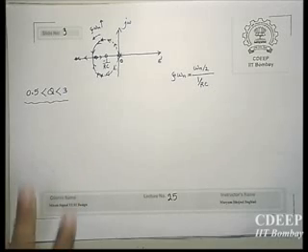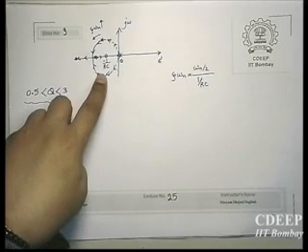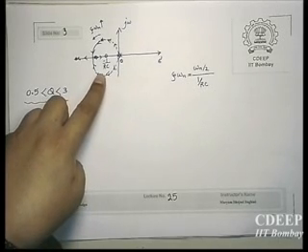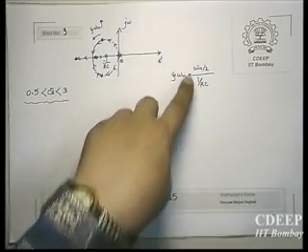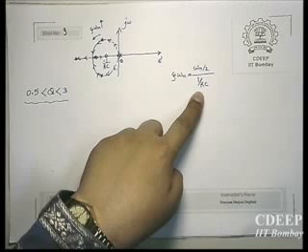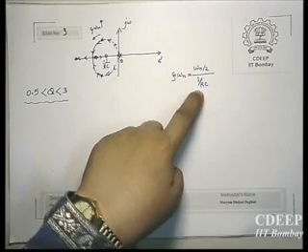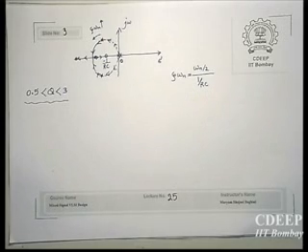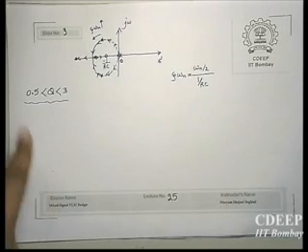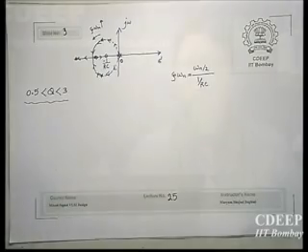For a given omega n, you are increasing RC to do that. This means that you are trying to improve the stability, but at the same time you are reducing the bandwidth. So that's why a Q between 0.5 and 3 will be okay to handle this trade-off.